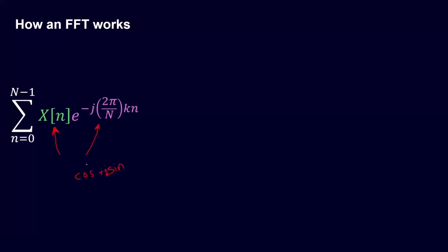The complex value is really just how much is correlated to a sine wave at that particular frequency, and how much is correlated to a cosine wave. Now, a lot of people think that if you get a complex number out of the FFT, usually in the form a plus bi, the real part is the magnitude and the imaginary part is the phase.